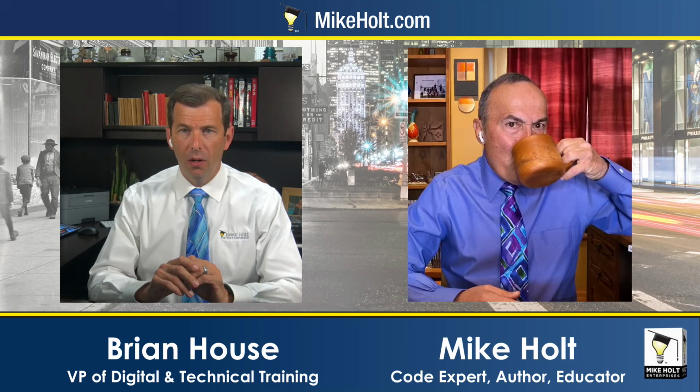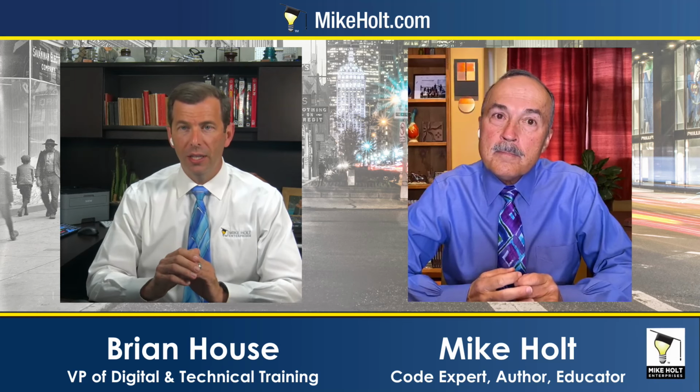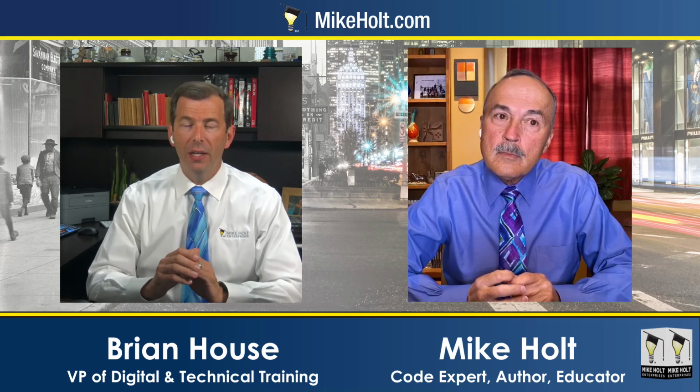Brian, you got more experience than I do on this. Who puts in the point of attachment? Does the utility ever actually go to the riser? It varies by area. To be honest with you, there are many areas that we've worked in over the years where we're required to put in a point of attachment, especially if it is overhead to a commercial service, then the utilities want an engineered point of attachment. Residential, it just varies by utility, and they do sometimes come in and attach directly to the service mast.